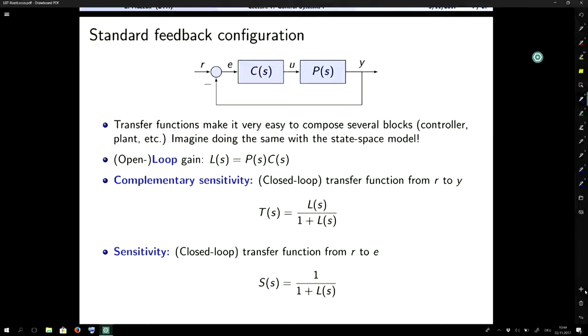Remember, this is only valid in the case in which your system is stable. But then, let's say that R is equal to 0. Then E, the error, where this e is not the basis of the natural logarithms, will be just minus Y, which is equal to minus P of S times e to the power st.